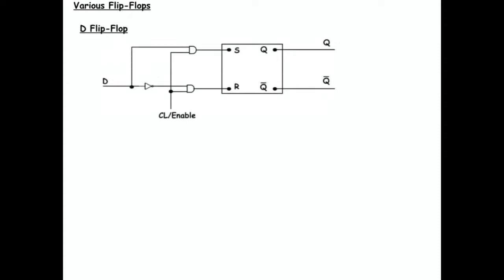OK. So let's look at what is called a D flip-flop. This is closer to what happens in real life. Here we have our regular flip-flop gate, but there are some other externalities involved. The biggest important externality is that in real computers, everything is done on a system clock. So we're going to treat the system clock as a controller.